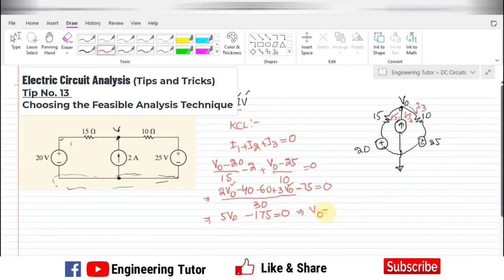we can see that the value of I1 plus I2 plus I3 is equal to 0, or V naught is equal to 175 divided by 5, which will ultimately give me the value of 35 volts. This is the value of voltage which I have to find out, or which is required by me. Now as I have found the value of this voltage, I can easily find out the power dissipated by this source, and that is basically the 2 ampere, and the value of current here is 2 multiplied by the voltage across, which is 35, so this is now 70.